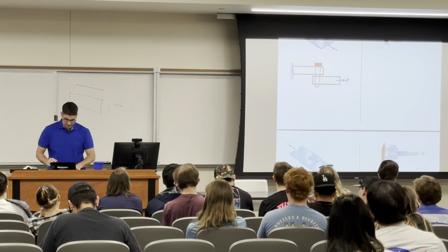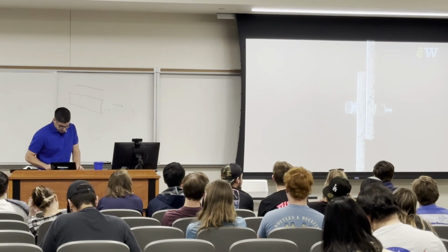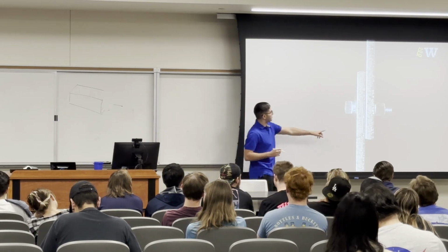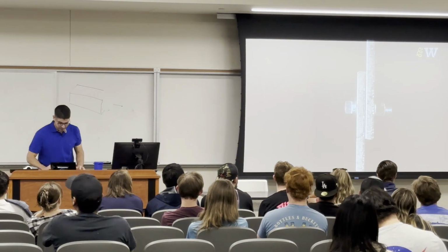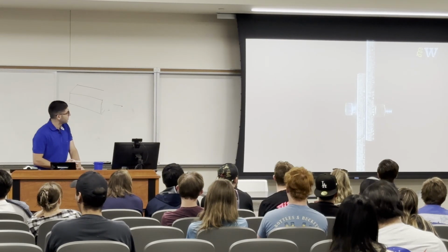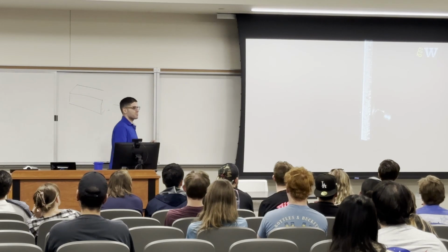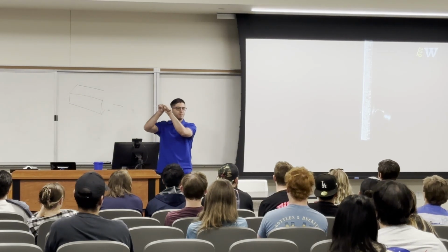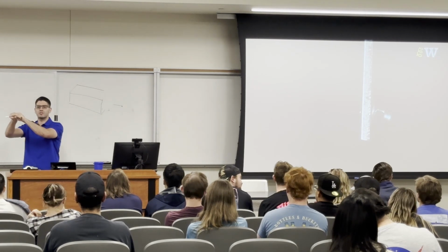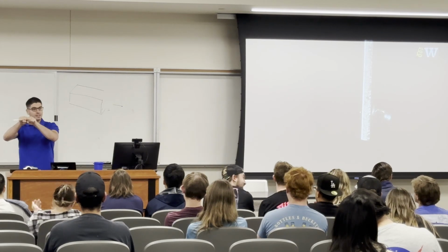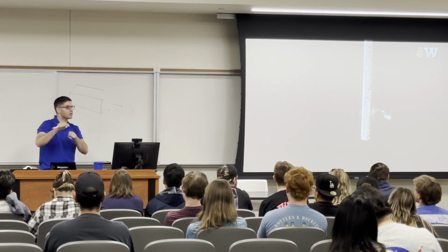And let me show a video that explains this more. So same example. I have two plates. This one is fixed to a wall, and this one is going to be pulled down. I want you to see the failure, how it's going to happen. What do you think the bolt itself experienced? Did the bolt experience tension or compression, or some sort of friction? Shear. So the force was parallel to the bolt. So the bolt couldn't resist all this force. That's why it broke in shear. It didn't break in compression like it buckles. No, you saw it broke parallel to the cross section. That's what we call shear.